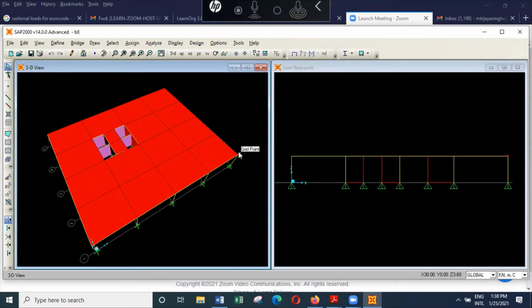Any other question? Because a cantilever is a statically determinate component, the final effect of the cantilever is to add more load onto the particular beam that is supporting it. So in the model, you don't model the cantilever, you simply model the load, because the cantilever is not going to give any stiffness to the beam. If a cantilever is going to stiffen the beam, then you have to consider it that way. Okay, sir. Thank you, sir.